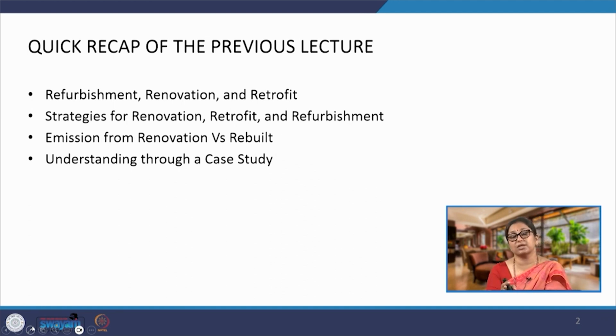Now, before I move on to the case studies, we have to clearly understand what these emissions are. As we have clearly seen, the maximum amount of emission from buildings as assets is going to be scope 2 emission, and scope 3 emissions are also there, which are embodied due to the use of the materials. So, it is through the value chain. The kind of materials that we are using will influence scope 3. We are usually not looking at scope 3 emissions. We are looking at scope 1 and 2 mainly, of which scope 2 forms the most significant part.